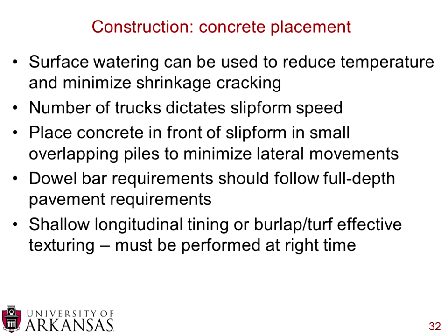When you're placing the concrete in front of the slip form, you want to make sure you have small overlapping piles. You don't want a whole lot of lateral movement of material. Lateral movement can cause segregation, which is not desirable. And also, if you're going to put dowel bars into your overlay, you should design that dowel bar placement as if you were doing a full depth pavement requirement.